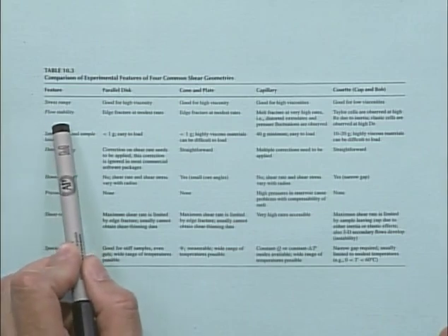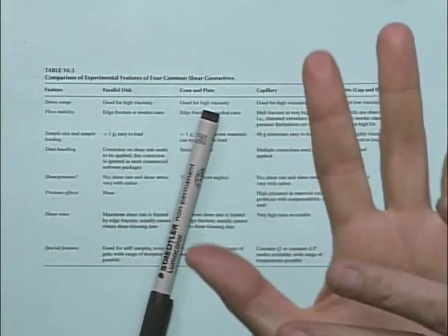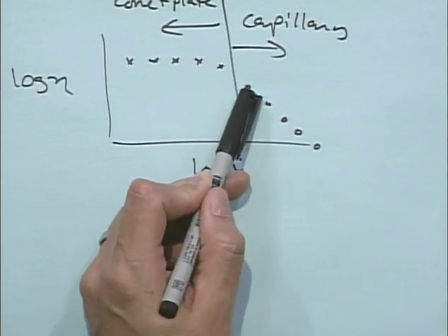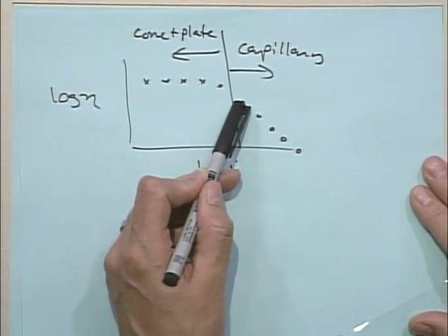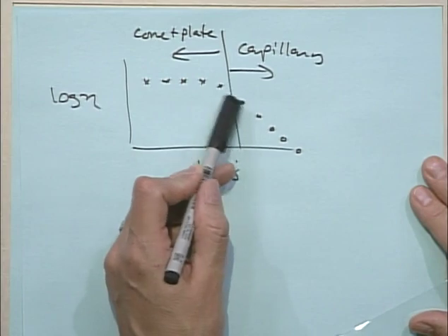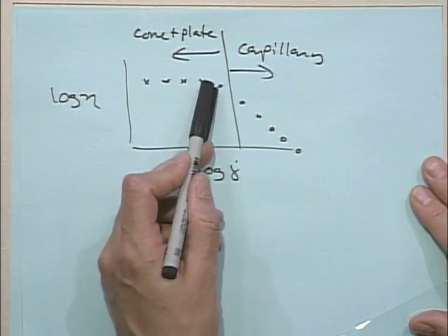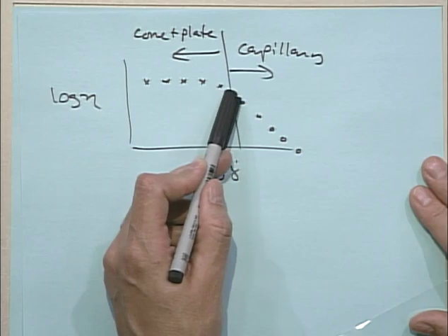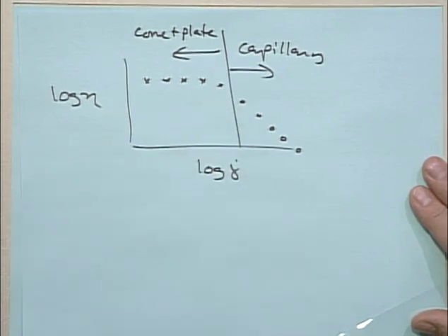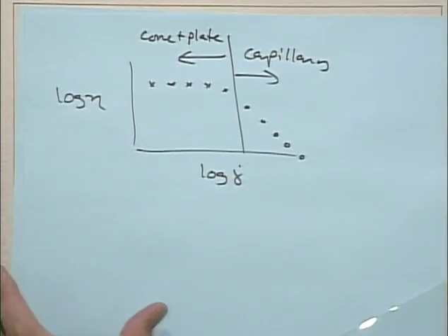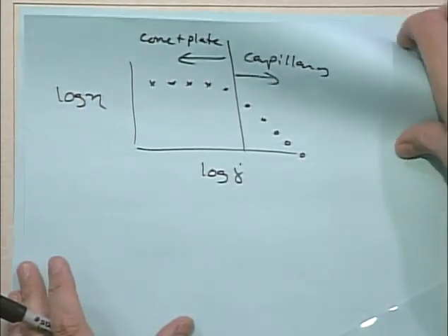One is a discussion of flow stability. So the parallel plates, at steady rates, there can be some edge effects. And those edge fractures are actually the reason why we end up not being able to go to the highest shear rates in the cone and plate or the parallel plate. Once you get out to these high shear rates where it starts to shear thin, the edges become quite distorted, and in fact, sometimes the sample actually exits from between the plates.